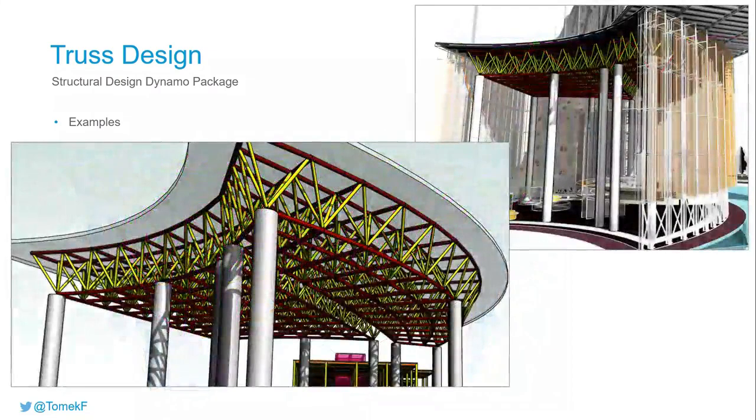And this is an example of usage of the spatial truss node in Revit. What I did, I selected this roof deck, converted its geometry into boundary curves, and my input for spatial trusses, they need some curves or points. So I had everything to generate that in Dynamo first.